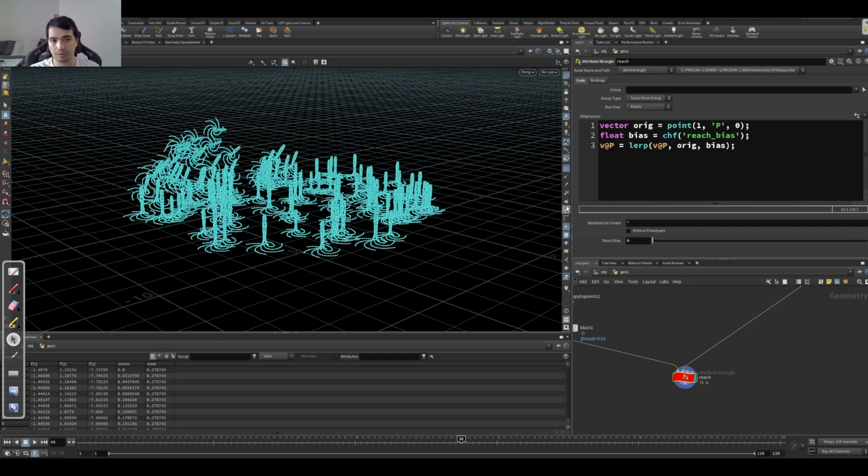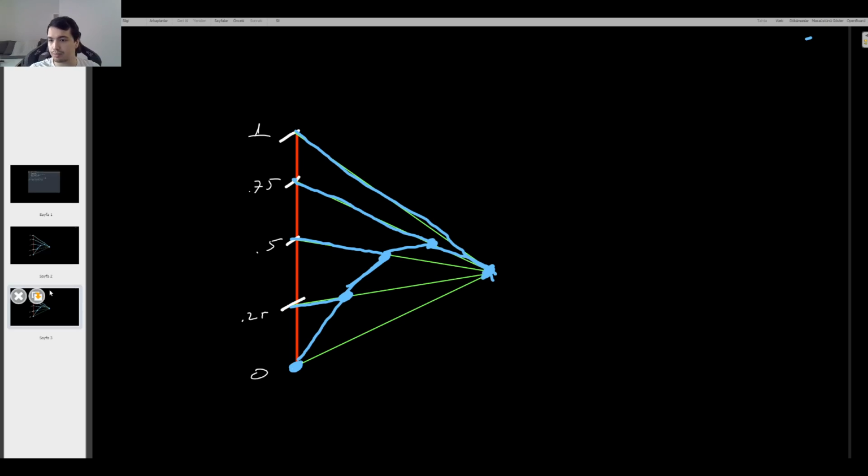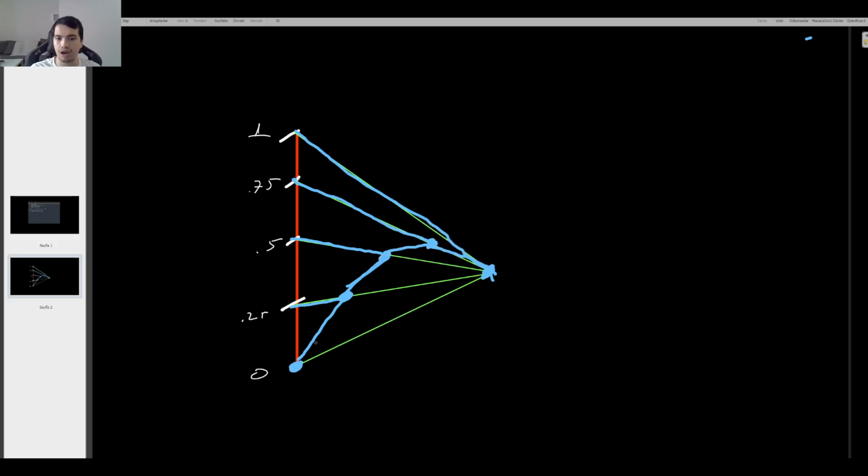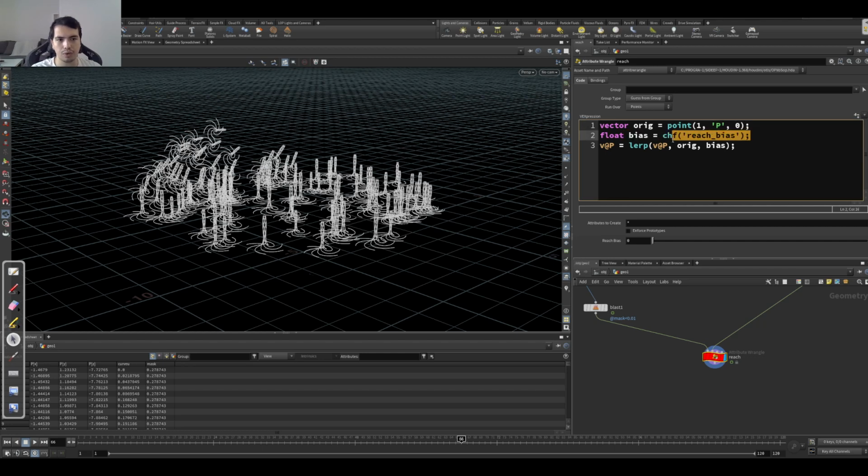Now I didn't want that. I want them to use their curveu attribute as a power for how much I'm going there. Yes, we can create that one as well. This is Houdini, let's go for it. You see this bias, I create a float. Now I don't want this float to be used, I want a different approach using curveu with a ramp.